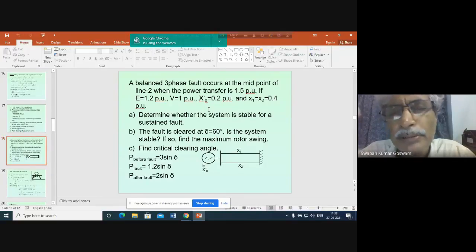Now the damper winding is a short-circuited winding, and the field winding is supplied by DC. So in the field winding of the generator there will be the normal DC current flowing, but over and above this DC current there will be another EMF induced because of the change in the flux due to the armature current of the generator.